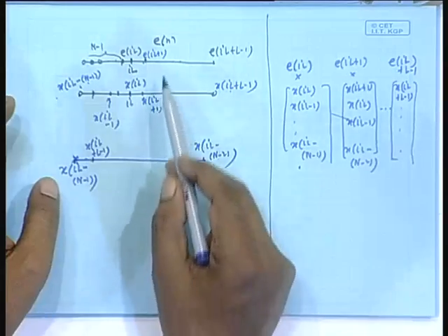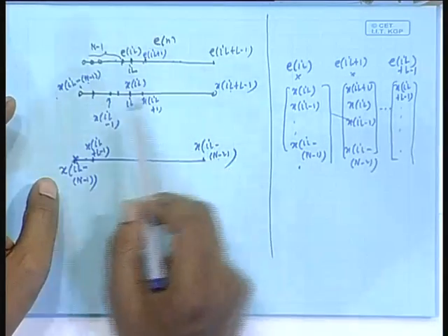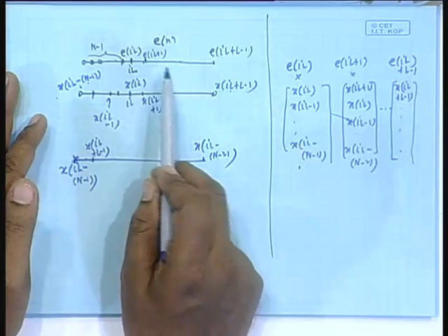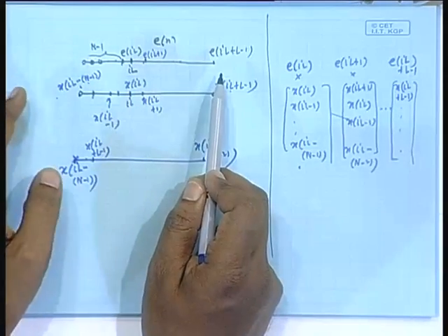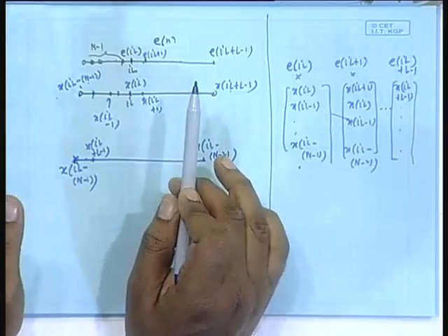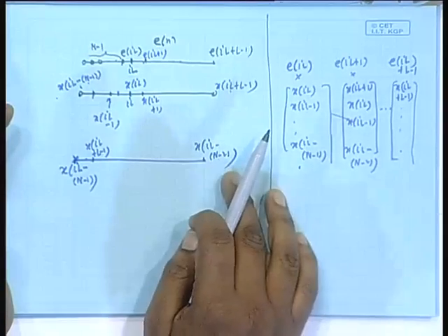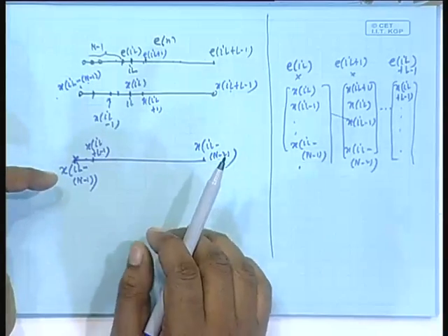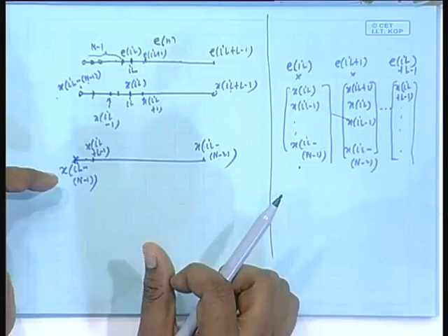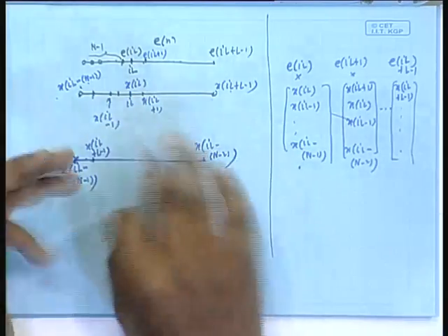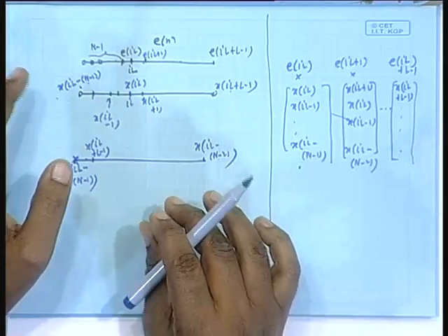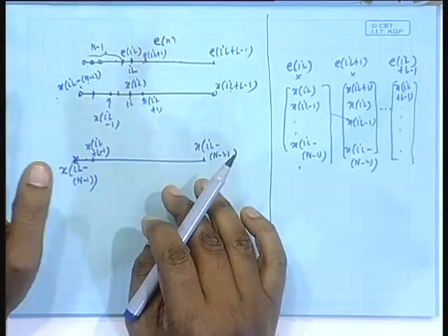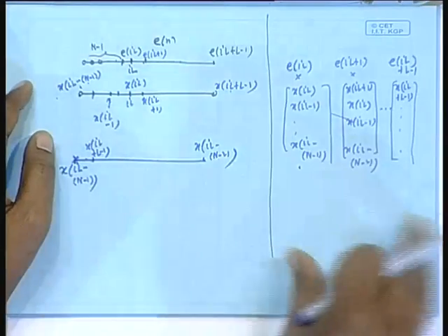So, that means I have to do a circular convolution between the two. What is the DFT of this? Okay, I can take the DFT. You give me the E sequence, error sequence, I add some extra 0, maybe make it a bigger vector of length capital M. I can take an M point DFT of that. But how about this guy? It has got some extra data. Earlier I was living happily with L point data vector. Now, some extra garbage has come and they have got flipped and order has been changed and all that, isn't it? So, what do we do to that? That is the question. Now, I show you some beautiful property of DFT.